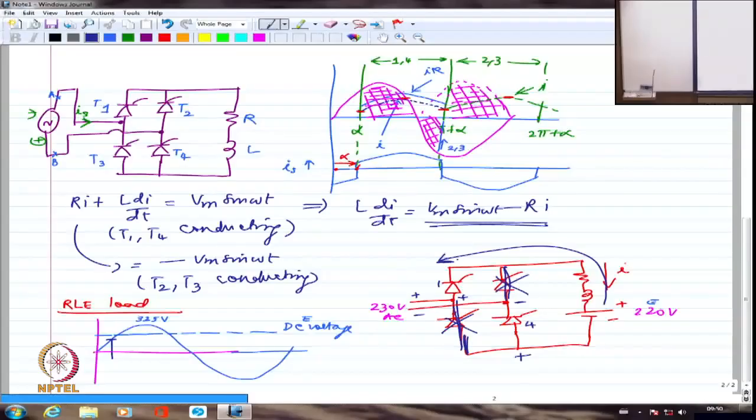When there is no current, there is no drop, so this voltage will appear right there. Then I have a tug of war between these two, whether this is dominating or that is dominating. If the voltage that is here dominates over this positive, then it is reverse biased. On the other hand, if this is smaller, I will have this forward biased. The same thing holds good for the other device as well. So there are two cases we have to consider.